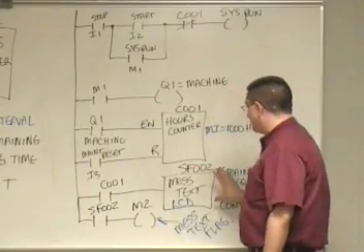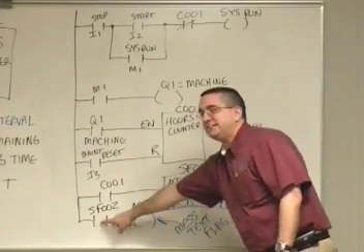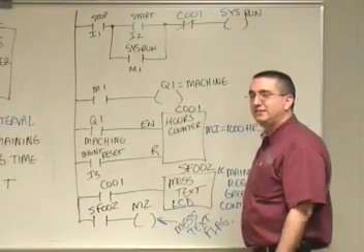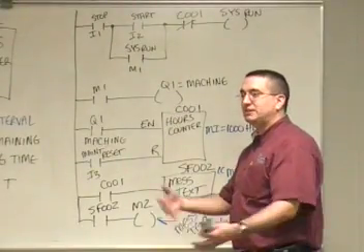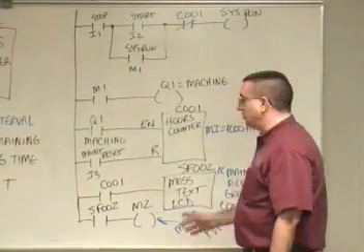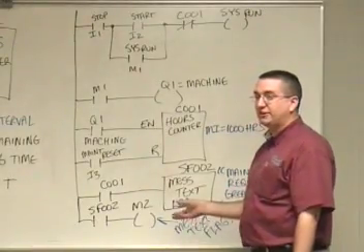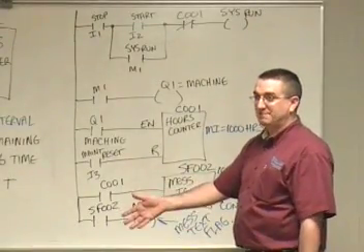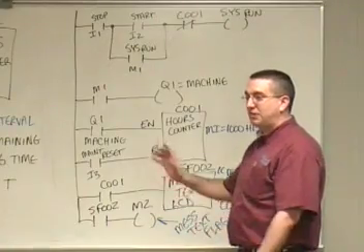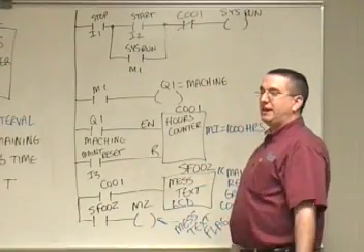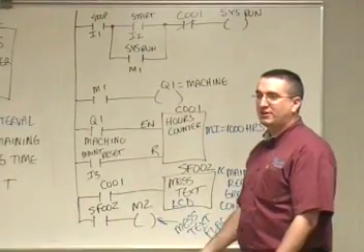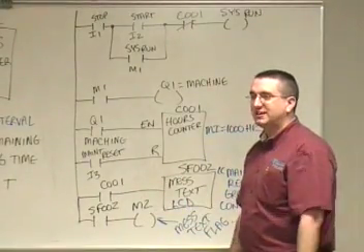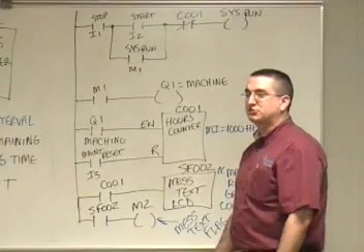Well, guess what it does on this block if I don't have a contact addressed to that block? It gives you the error message. Guess what that error message is? Blocks without a connection to an output. It'll happen to somebody in here on the performance exam. They'll have a "blocks without connection to an output" error, and they'll sit there and spin their wheels and not figure out why they can't get their program to work. And Jeff will come over and you'll ask him, and he'll say, "Ooh, you should be able to figure it out, troubleshoot it."